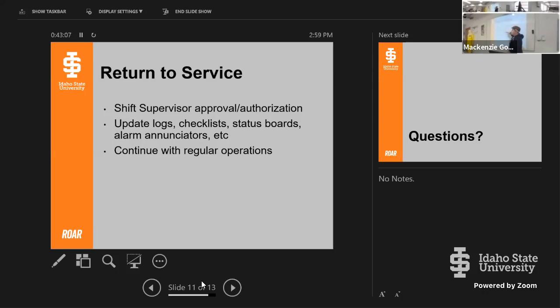So you have to clear existing alarms when you put something back in service, especially if it's something that gives you an alarm when it's out of service, because you have to be able to receive this alarm if you're operating and a system you have to have suddenly breaks, right? We took it out of service to do maintenance. You knew you were going to get that alarm. That's part of the process of them telling you they're going to do this temporary mod.